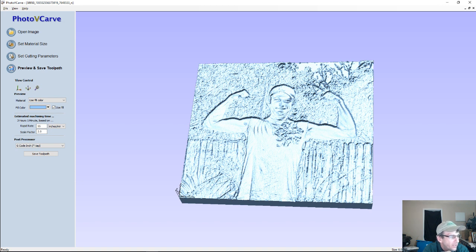So if you don't want to chisel out those corners and all, then use an 1/8 inch bit to cut it out. If it's thicker wood, maybe like 1 inch thick, and your 1/8 inch end mill doesn't cut that thick, then it's kind of irrelevant to be using a smaller end mill anyway, because most of them only have a 1/2 inch cutting depth and things like that. So you use your bigger end mill and you do some tool work afterwards. So no, in my honest opinion, it's not worth it.